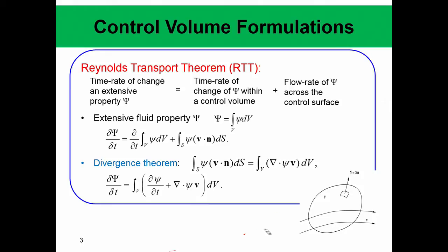Of course, we can go into this in detail, but this is not a fluid mechanics class or a thermodynamics class, so we will just leave it here. It says that the time rate of change of an extensive property xi, please note, which is within a system, is essentially equal to the time rate of change of xi within the control volume and the flow rate of xi across the control surface.